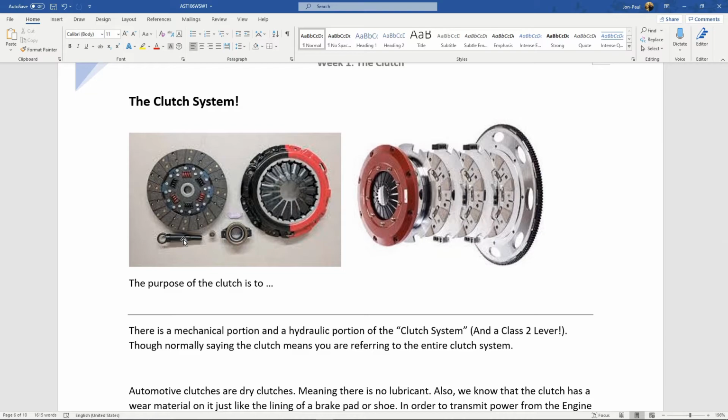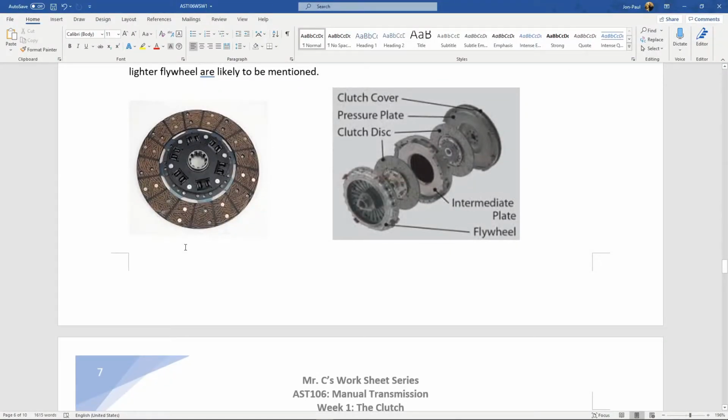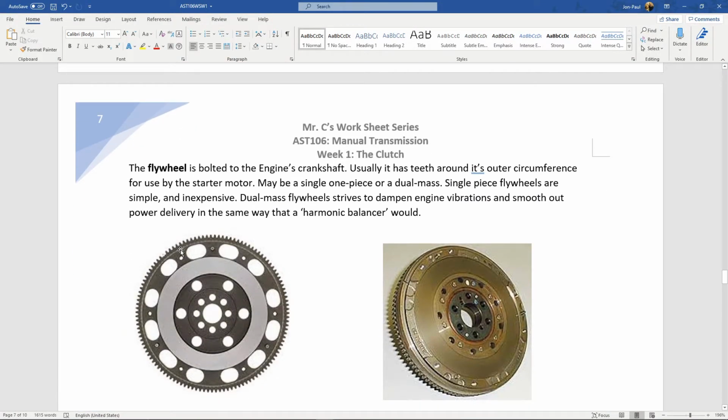You've taken everything apart. You've sent the flywheel to the machine shop to have it machined. It's come back looking pretty. And also, since we're here, the rear main seal on the engine is right behind this flywheel. You should always try to upsell this and tell the customer, look, it's $30 for the seal. I'll only charge you 0.3 to install it. And it would be a shame if you just had your whole clutch rebuilt and then 20,000 miles from now the rear main seal starts leaking, because then I have to take all this back apart, because the rear main is right behind the flywheel.